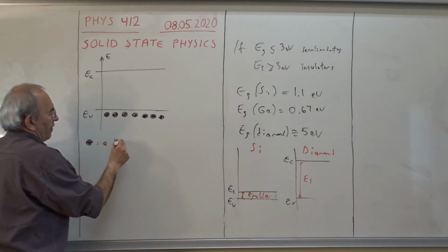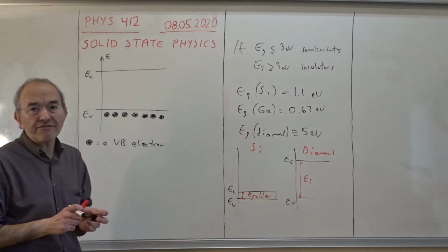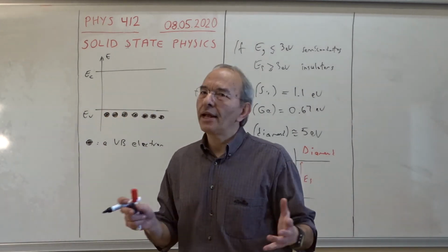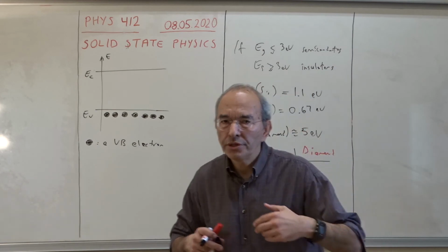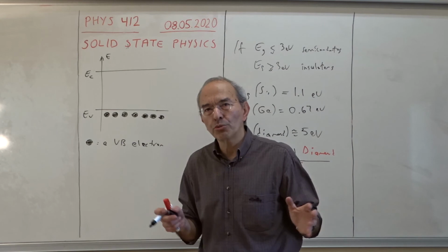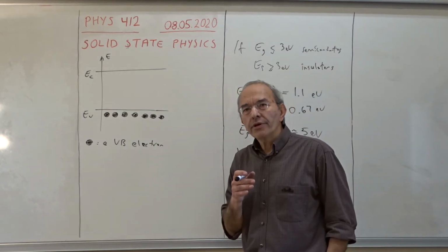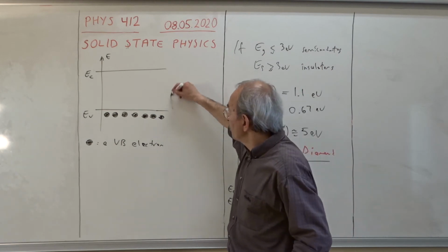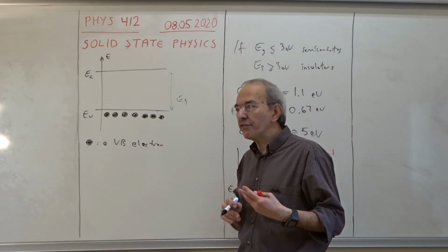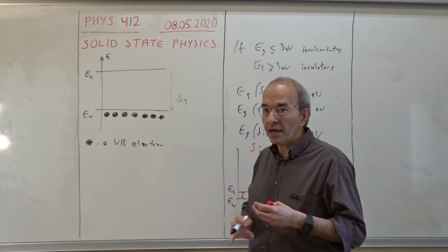A valence band electron. What is the meaning of a valence band electron? This electron is just staying in an atom. It is not detached from the atom and moving around randomly, so it doesn't give any contribution to the conductivity. Alright, if this much energy, remember this much was Eg, energy gap, is supplied to one of them by some means, by which means?